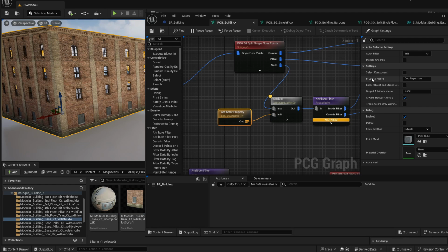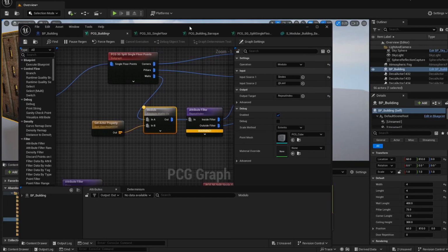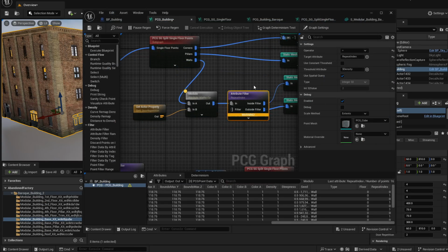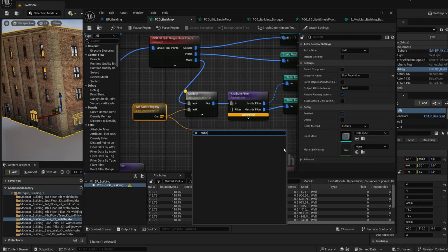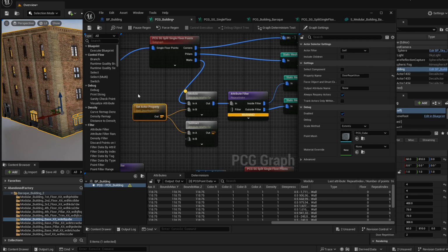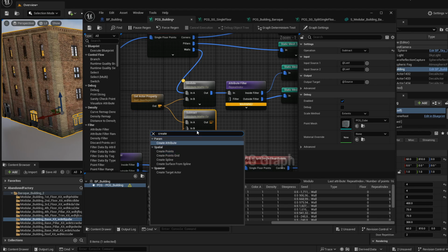We are getting the door repetition property. We are dividing it into this modulo. So currently the door repetition is set to 0, as you can see. That's why we don't have any results. Now I do need to calculate this threshold, not to use a constant threshold. So I'll get this property and I'll subtract 1, because when you divide by, for example, 4, the maximum remainder that you can get is 3. So I'll subtract 1.